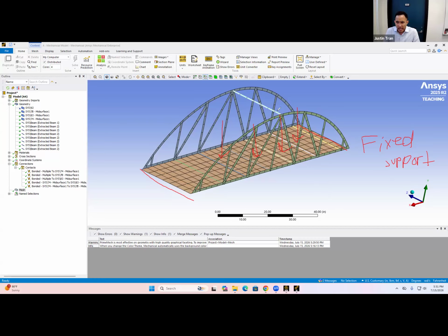Once you do that, you can run your simulation, and just like normal, you can display things like the total deformation and the equivalent stress. Once you display those, you can see your results from there. You should see that the results actually look pretty good. Even though we have two-dimensional elements and one-dimensional elements, you should be able to see that our elements are deforming out of plane, which is exactly what shell and beam elements are supposed to do.